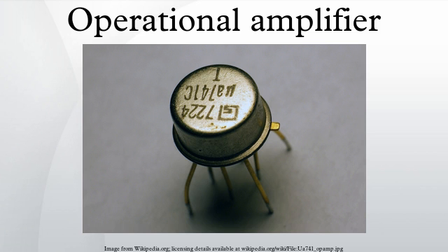Closed loop. If predictable operation is desired, negative feedback is used, by applying a portion of the output voltage to the inverting input. The closed-loop feedback greatly reduces the gain of the circuit. When negative feedback is used, the circuit's overall gain and response becomes determined mostly by the feedback network, rather than by the op-amp characteristics. If the feedback network is made of components with values small relative to the op-amp's input impedance, the value of the op-amp's open-loop response AOL does not seriously affect the circuit's performance.